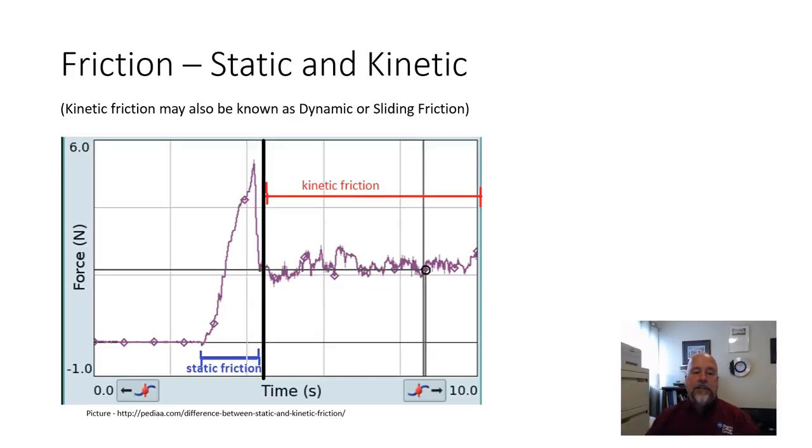Okay, so friction. You've got static friction and kinetic friction. Friction goes on forever. If we look here, we see our static friction. There's no movement. Here we're applying some force. You have to apply a significant amount of force before things start to move. Once things move and you get one thing sliding against the other, you're into the kinetic friction area. So you see we're applying force here, but we have no movement, and then at this point we get movement, and the amount of friction between the two things drops dramatically. So you can translate this directly to the grip of the tire on the road.